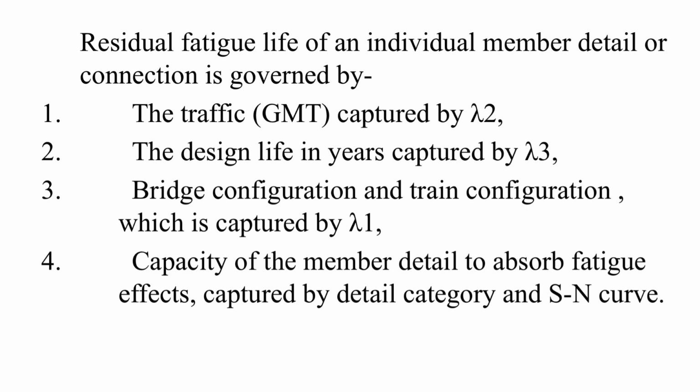the bridge configuration, that is, what is the arrangement of various members in the bridge, the train configuration, that is, what kind of trains are flying over the bridge, and the capacity of the member detail to absorb fatigue effects. If we look carefully, we will find that volume of the traffic is being captured in calculations by factor lambda 2.